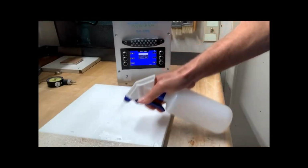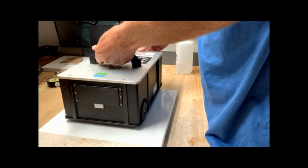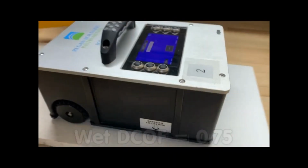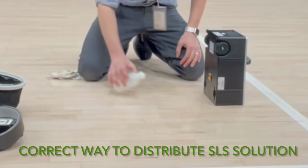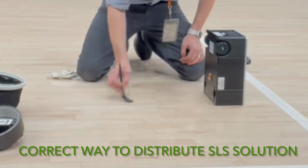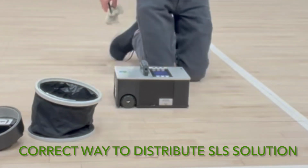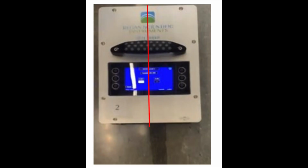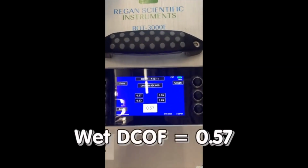Here are some examples of what not to do when slip testing with the BOT 3000E tribometer. A spray bottle is not the appropriate way to distribute SLS solution onto a substrate. Standard test methods require SLS to be evenly distributed with a brush. Make sure that enough SLS solution is distributed evenly and that the BOT 3000E is placed over the distributed SLS so that it measures the contaminated surface. This example shows a BOT that is placed in an incorrect starting position, which will not provide accurate DCOF measurements.